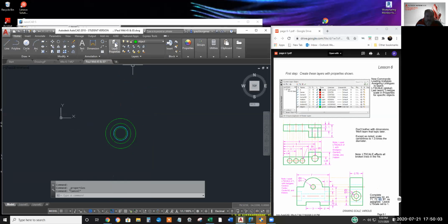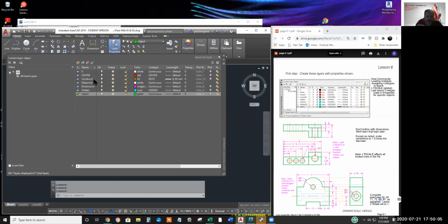Since I let the construction layer survive, I'm going to draw chalk lines on the construction layer. If I ever move or scale the project, I'll have to remember to thaw the construction layer, otherwise it's useless and I need to erase it.